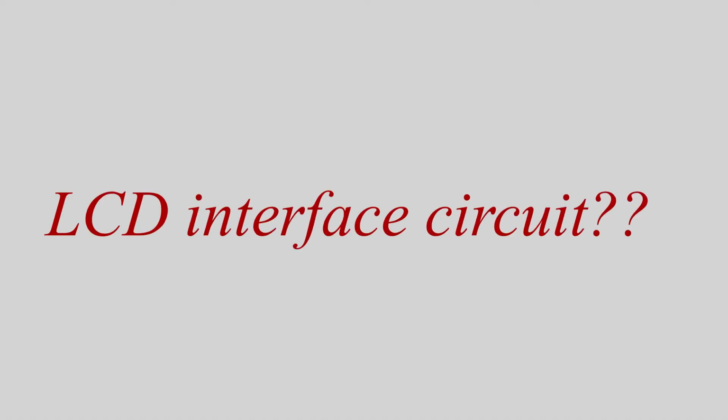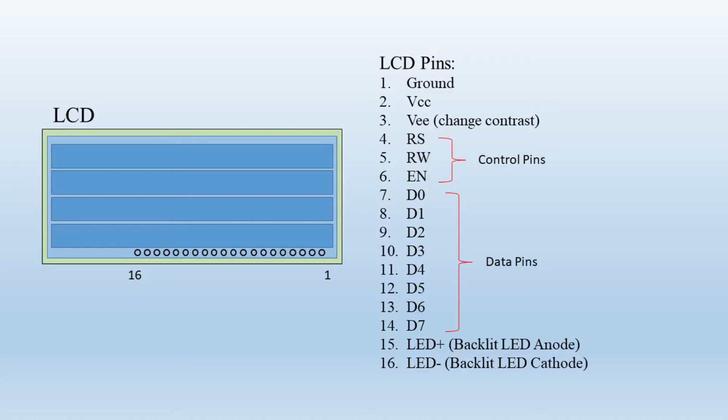Now let's see the LCD interface circuit. The alphanumeric display has a total of 16 pins for the connection with the controller. The total 16 pins are mentioned here, out of which the first pin is ground, the second pin is connected to VCC, the third pin will be connected to VEE for changing the contrast of the LCD. The 3 pins RS, RW and enable are the control pins. The 8 pins D0 to D7 are the data pins and the remaining 2 pins are for the backlight LED.